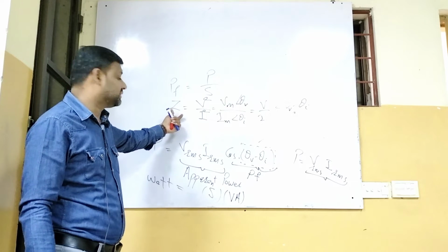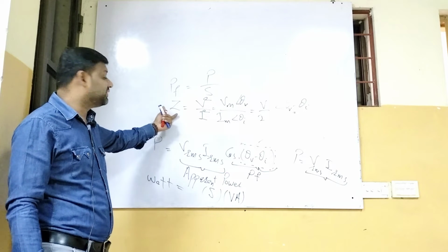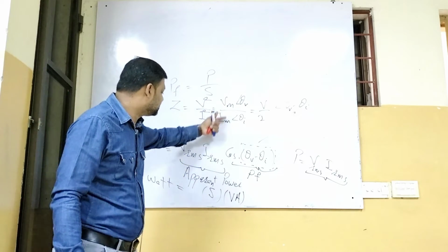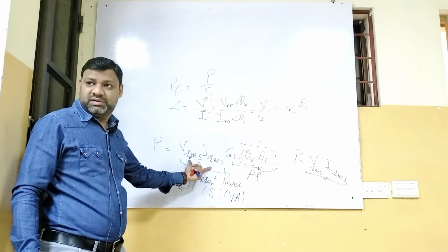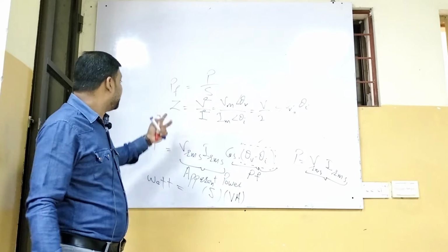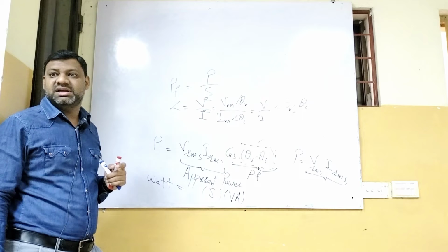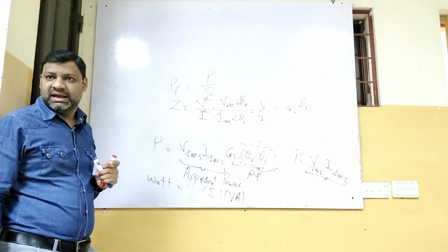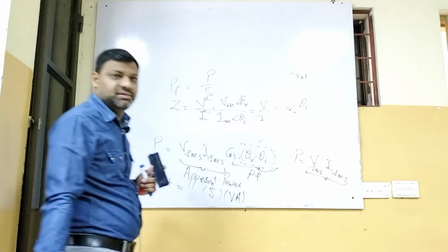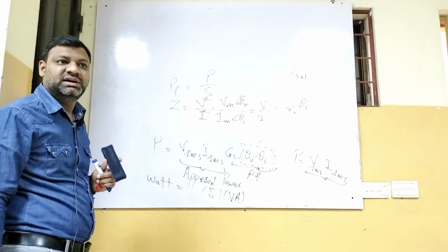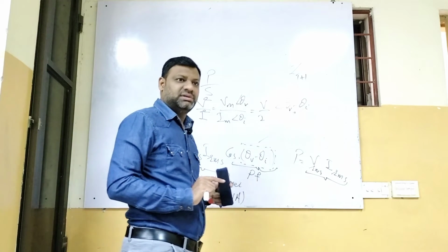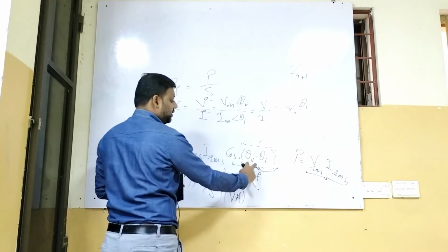If someone asks what is the power factor of this circuit, and none of the things are provided, equivalent voltage or equivalent current, the power, then the other way is to find out the equivalent impedance of the circuit, and you have already found it through Z Thevenin, the total impedance provided by the source at the load. Here we are again talking about that.